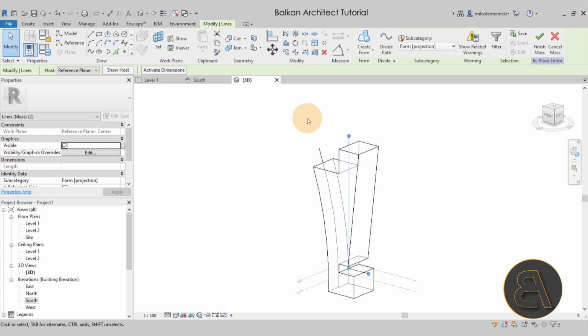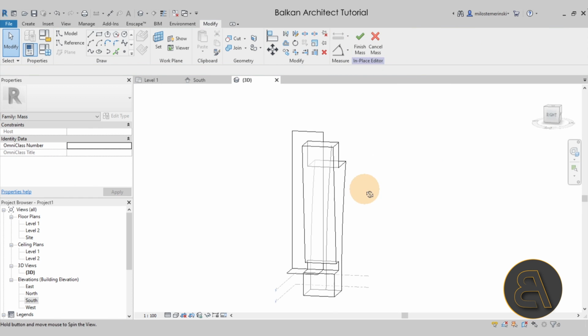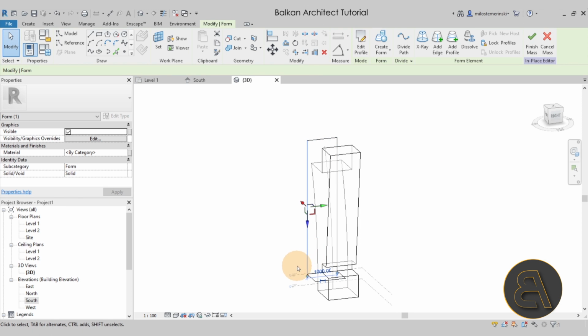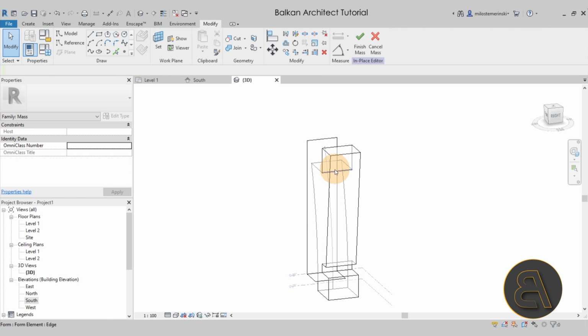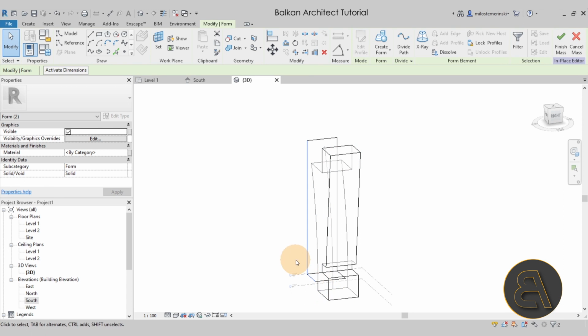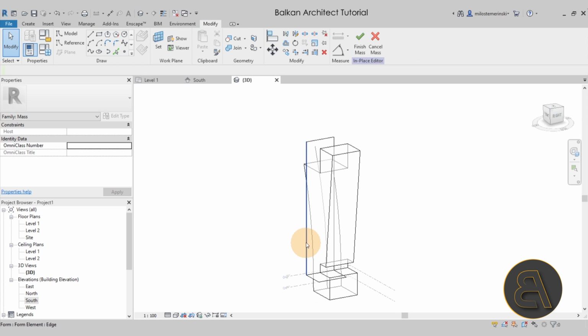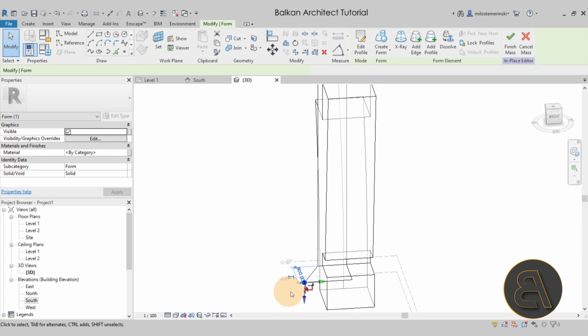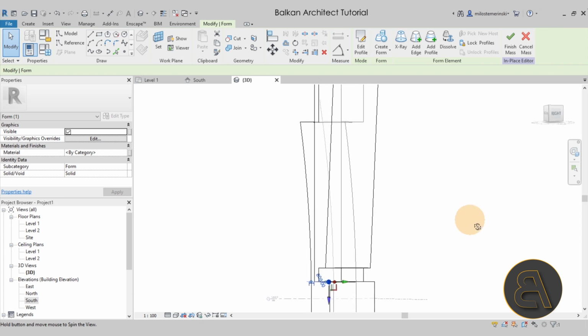And then we can extrude that by going to create form, and it's going to extrude it like so. Now you want to select that whole side. This is a little bit trickier than with the shape we had before, because we cannot select 2 lines at once. Well, we can, but it's really tricky to work with them. So I like to select one of them and then bring it to, like 600, like so. And then you select this point and you just bring it in until it aligns. And there we go.